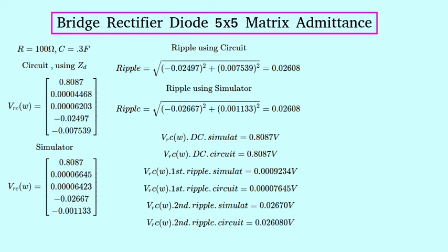Here is the ripple formula, just getting the root mean squares of all the different frequencies. The first ripple is for the fundamental frequency, which should be close to 0. It isn't 0 because of the imperfection of the simulator. It contains a bit of asymmetry because it used an odd number of intervals, being 51. The second is that for the second harmonic, which should contain the main ripple that we'd measure. So this is how we'd compare all of the results for varying parameters of this circuit.